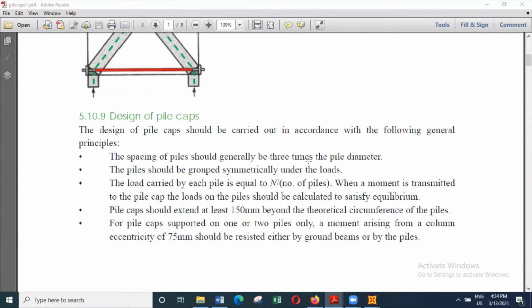So in our conditions, we actually rely on both cohesion or friction and end bearing. So it may be good practice to remain close to 3 times diameters if you cannot strictly follow the 3 times diameters rule, especially when you go for large diameter piles.